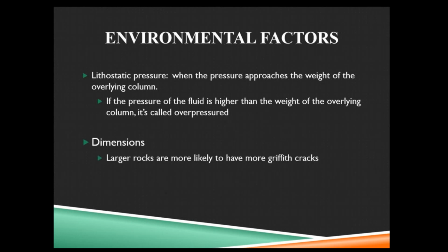Now, another important factor is dimension. Large rocks are going to have more Griffith cracks. There's more rock, therefore there are more imperfections. Very logical, but very important. The larger the rock, the more micro cracks, therefore the easier it is to break it. Again, seems counterintuitive. For us, like if we've got a little hammer, it's easier for us to break a small rock than it is to break a boulder.